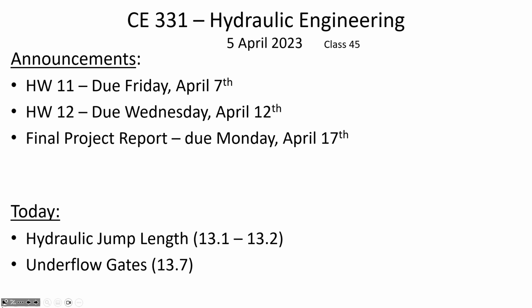And then for the reservoir, you need to interpolate the price from the given data. So I've given you a couple of sizes, I think maybe like 2,000 cubic meters and 5,000 cubic meters, but it doesn't mean that you're going to build only those sizes. So it's a little bit different from the pipes where you're limited to the commercially available pipes. For the reservoir, you can assume that you can build exactly the size that you need, which is the maximum volume accumulated multiplied by 1.25. But you get the price data by extrapolating or interpolating depending on whether you're outside the range of that highest value, in which case you just assume that the trend continues linearly, or if it's between the 2 points, then you just interpolate.